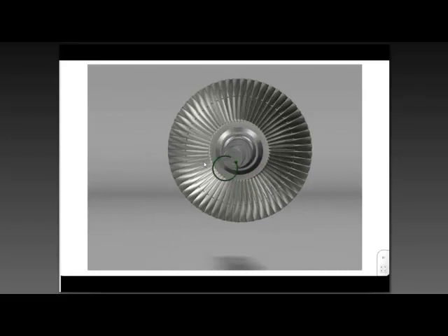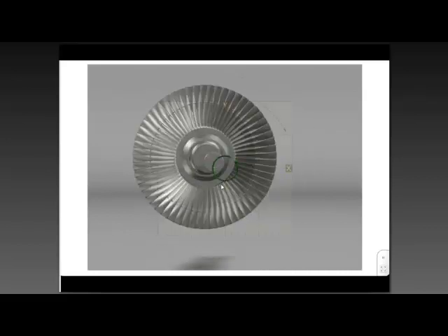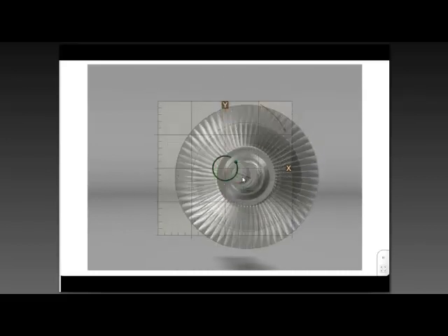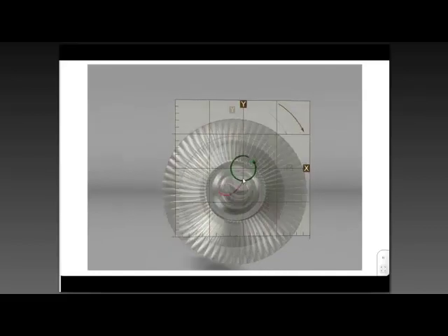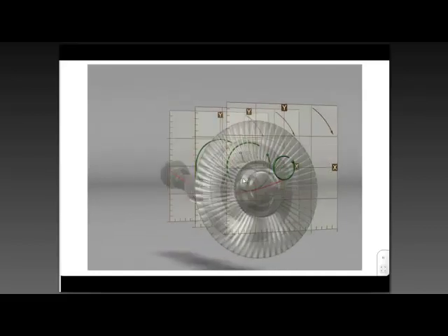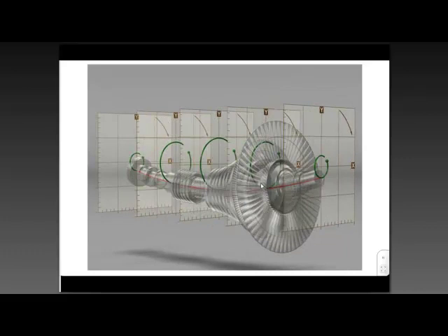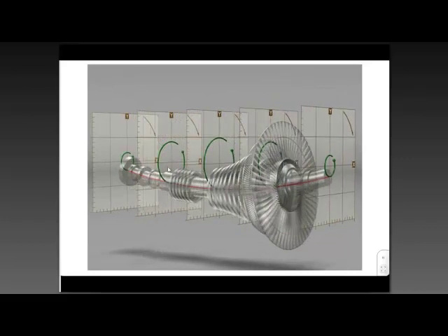That green shape you see is called an orbit. It's comparing the X vibration to the Y vibration. And if we were able to take multiple orbits along this shaft, we would see the shape of the orbit change. Now, that's just a real quick introduction. It's still using vibration analysis, but for this application, we do it a little differently.